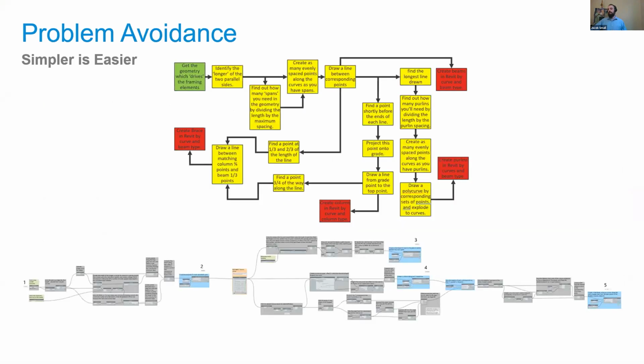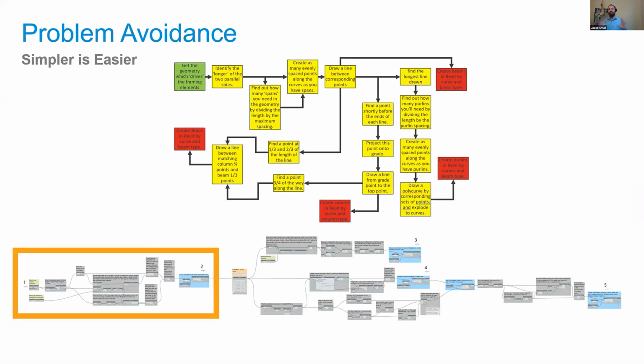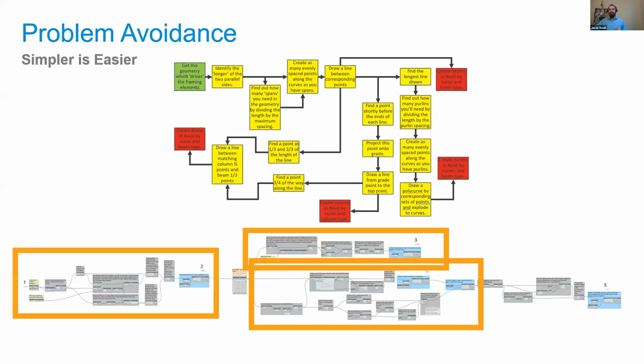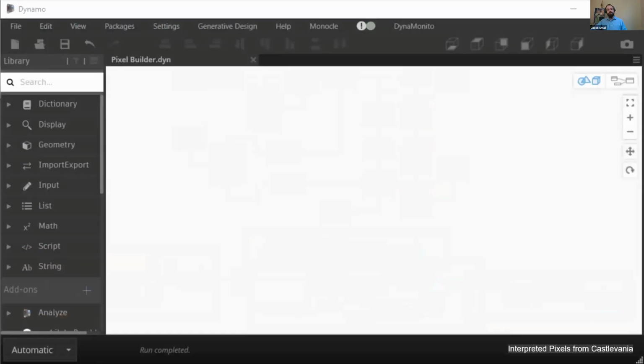One other example here, right? I showed this piece before. The way this graph actually built up, I started first by making this portion of the graph. That was the entirety of the graph. All it did was make the rafters, right? A couple of weeks later, somebody asked me, could we add it so it automatically generates the purlins as well instead of just the rafters? And sure enough, I added a new section to the graph. Some reorganization later, I said, you know what, while I'm here, I might as well make my columns too. Put that together. And then one day I said, what the heck, let's add a brace that ties the column into the rafter as well. All of that can now be automated, but each one of those individual steps was able to be leveraged in a project environment to save us time without having to automate the entire process. So that was really huge.